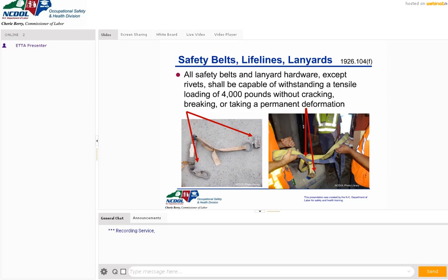Before you use it, while you're putting it on, make sure you do an inspection of your harness to make sure all the components are working. Make sure that in this case your clip works, that it locks. Make sure that this is a tensioning device that works, it slides up and it grabs hold. In this case, make sure your harness is in good shape. It doesn't have any snags, any tears, or any deformation. Make sure the buckles are all working. It's important. Make sure everything involved with those is in good shape.